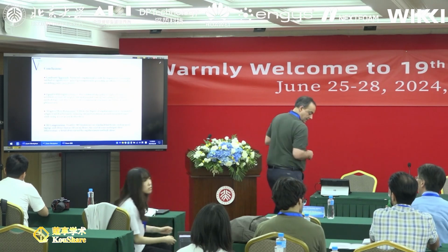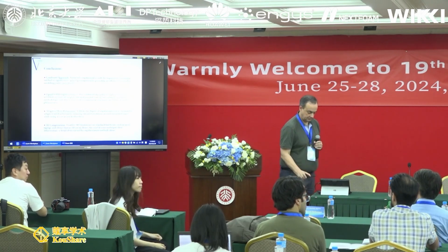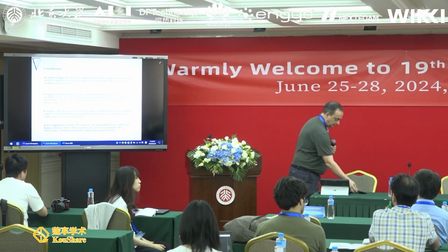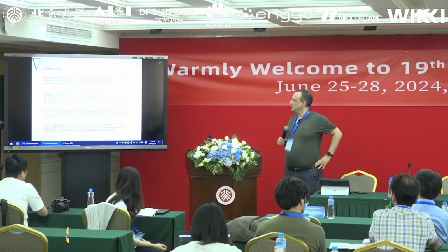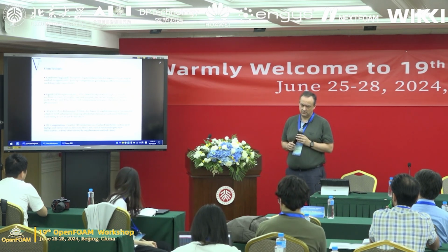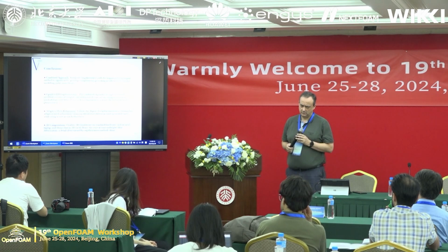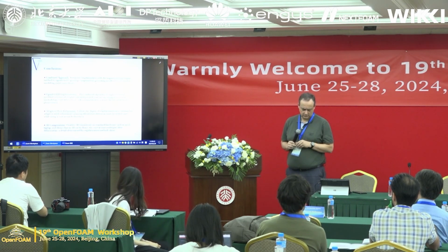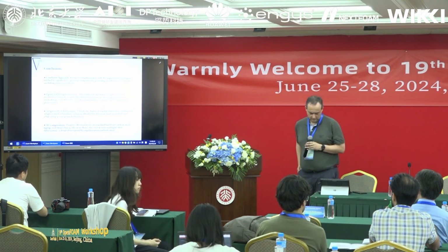Hello, thank you for your impressive work. Just a quick question, maybe I missed it during your presentation. I was wondering if your mesh adaptation algorithm is just geometrical or topological as well. While you actually refine the mesh, do you remove and add points, or do you just have the points with the same connectivity during your simulation?